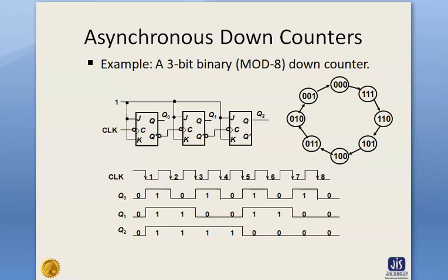Okay, apart from this, another two modifications are possible. One is making the flip-flop trigger on PGT instead of NGT, meaning positive going edge trigger.